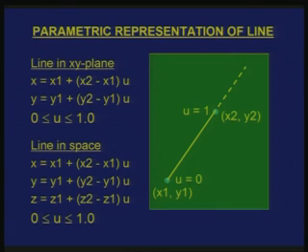But in parametric terms you can easily define a straight line passing through 2 points, or a line segment which starts at a specific point and ends at another point. So, here is a starting point x 1 y 1 and here is an end point x 2 y 2. So, I have a parametric representation where x is written in terms of x 1 and x 2, and it is also a function of a parameter u. And last time we studied that any functions of x, y and z which are functions of a single parameter basically represent a curve.